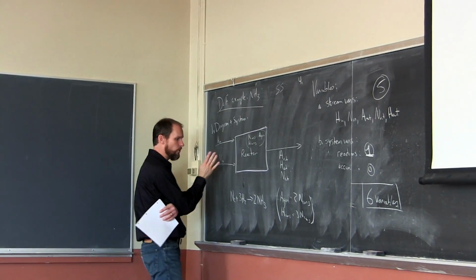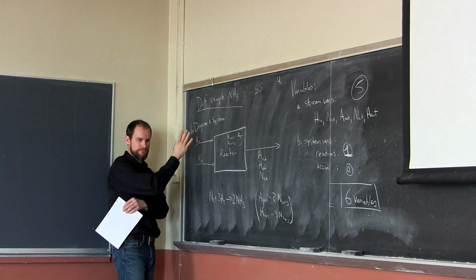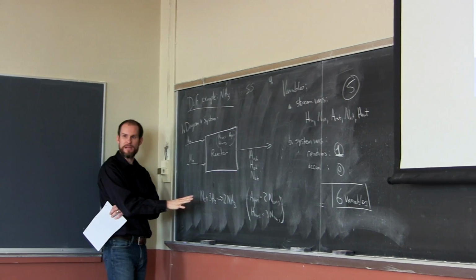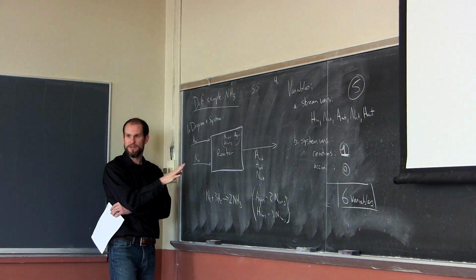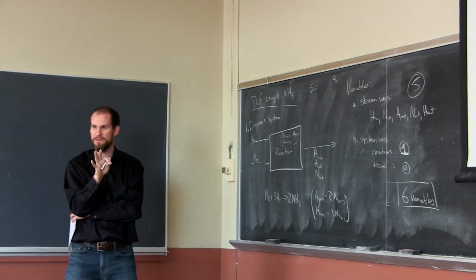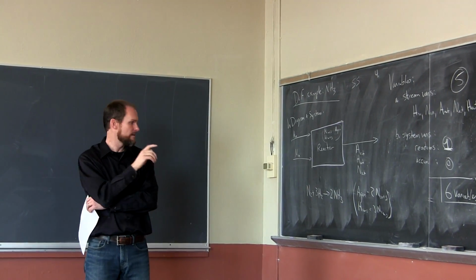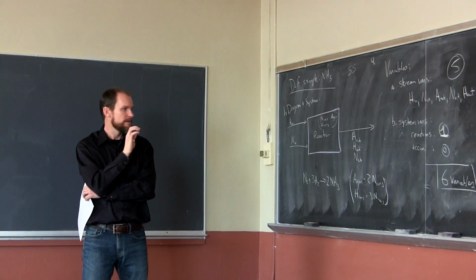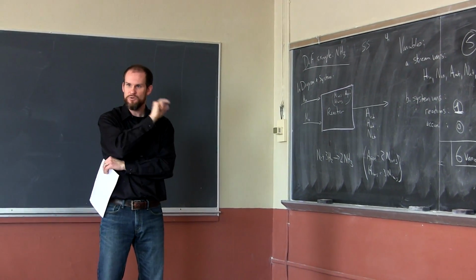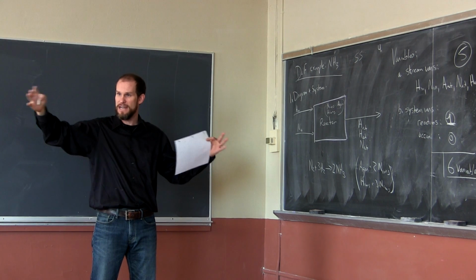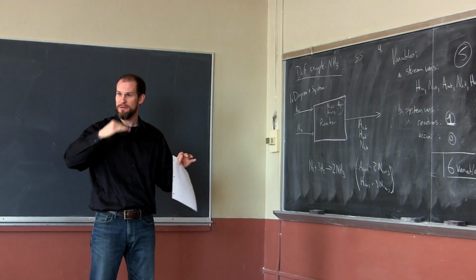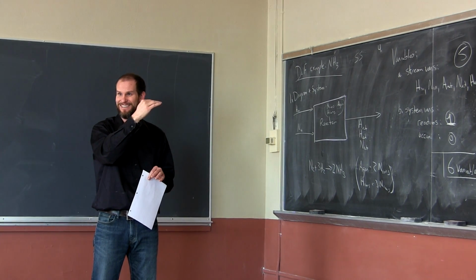So yeah, if I wanted to do the whole plant, which I could do 3 reactors with the 3 reactions, and I could list those 3 reactions, and I would count 3 in my degrees of freedom for the whole plant. We'll talk about that on Monday too. We'll do multiple processes on Monday. There are times when 2 reactions add up to a net reaction. Like remember the 3 reactions, we also had the net reaction for the whole process. That one's not independent because it's just the sum of the other 3.